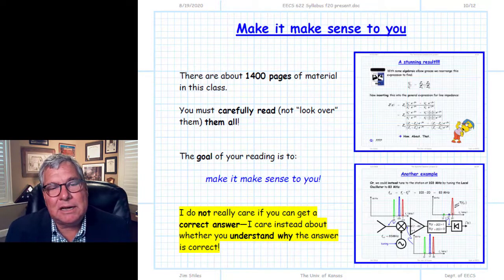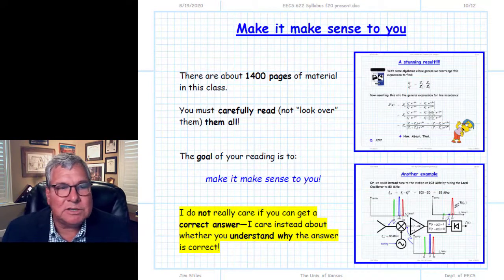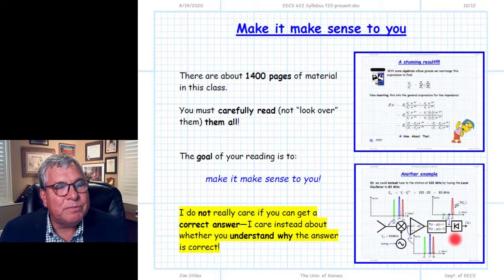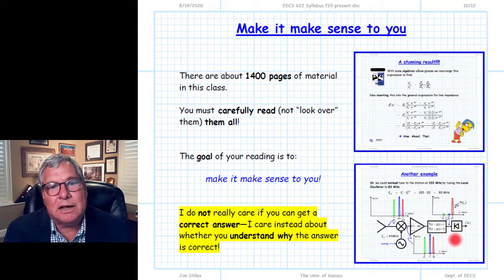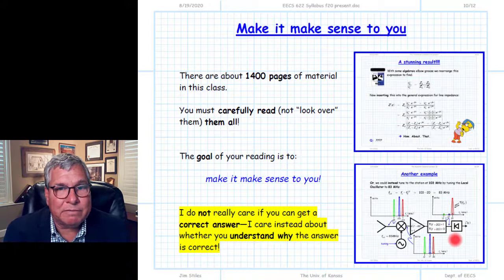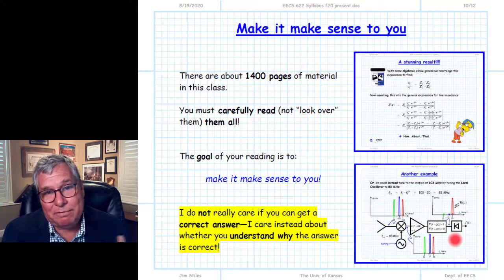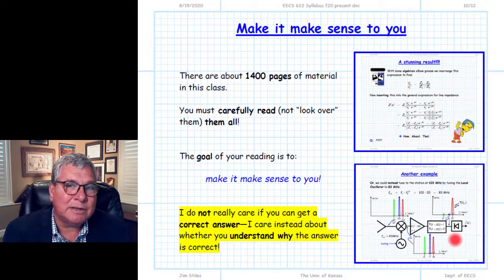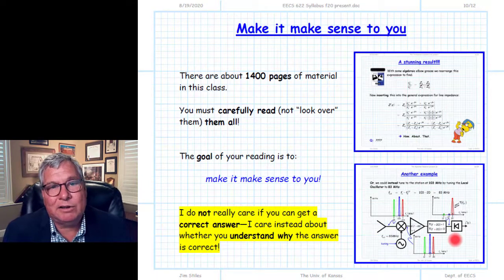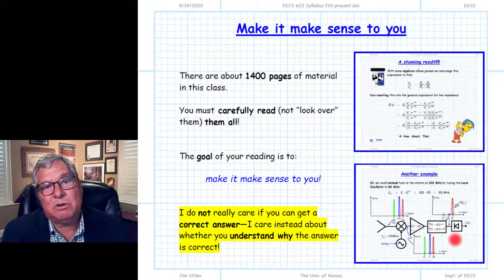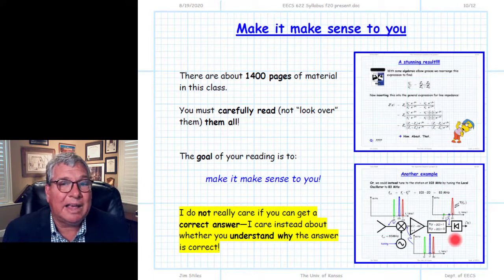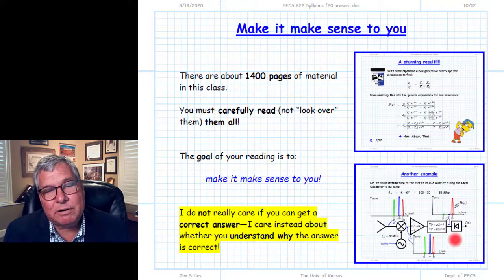This is a situation where if we look at a receiver, for example, we'll find it is a sequence of pretty simple operations where we change the frequency and/or power of the signals we're interested in, ultimately to a place at the end of the receiver where we have the right power and signal frequency that we desire, while simultaneously taking all the other signals that come into our receiver from other radio stations and moving them to a lower power and a different frequency far away from the desired frequency at the end.